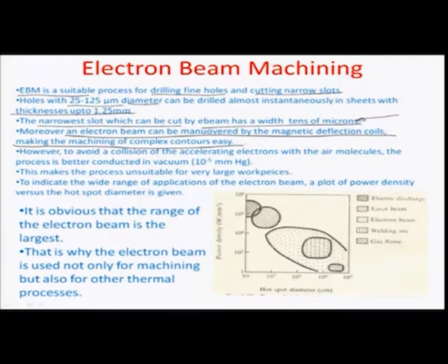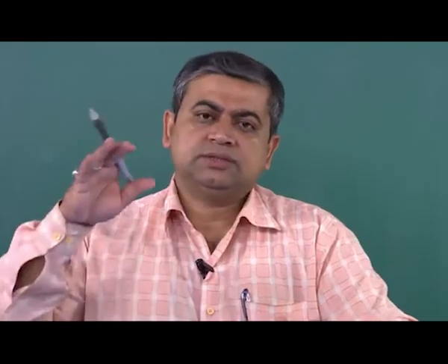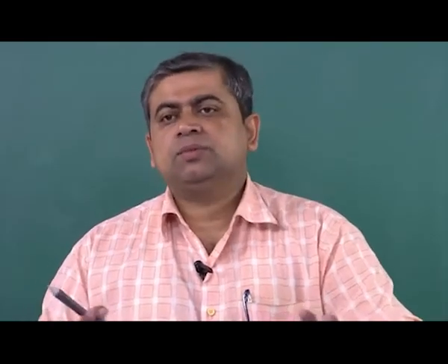So, it all becomes a matter of programming the topology of a surface on the beam direction, and direction can be controlled by suitably varying magnetic field in space. So, you have a lot more flexibility to raster the beam on complex shapes and features as well, which may not be the case in some of the conventional machining where metal to metal contact is needed.